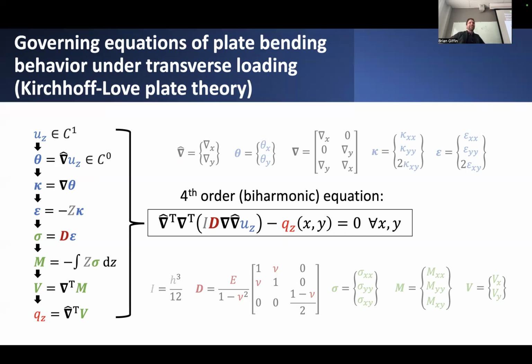back when we were talking about the Airy stress function and the requirements it had to satisfy in order to yield compatible solutions to some kind of two-dimensional problem of plane stress or plane strain, the actual equation it had to satisfy was, in fact, the biharmonic equation. So we've actually come back full circle.